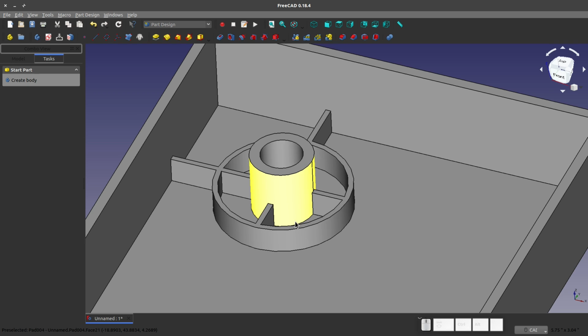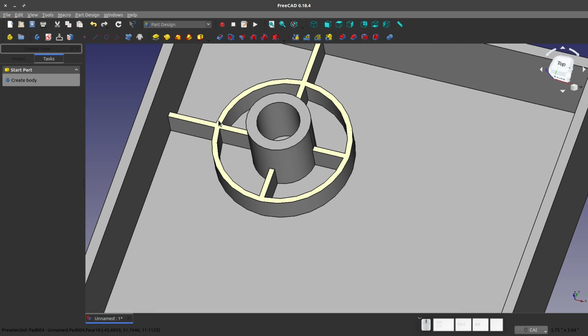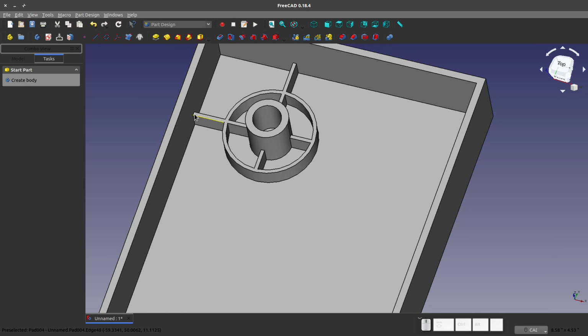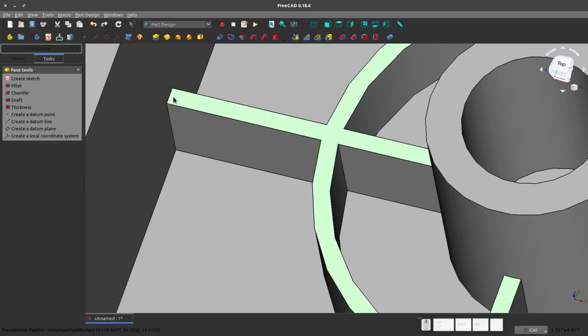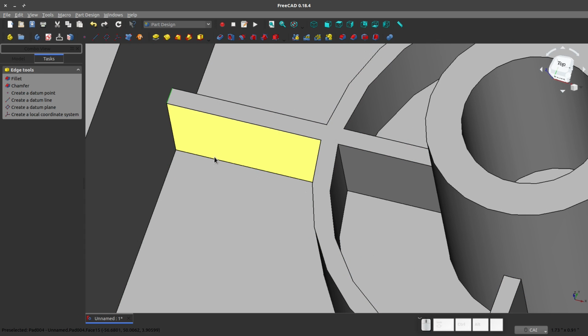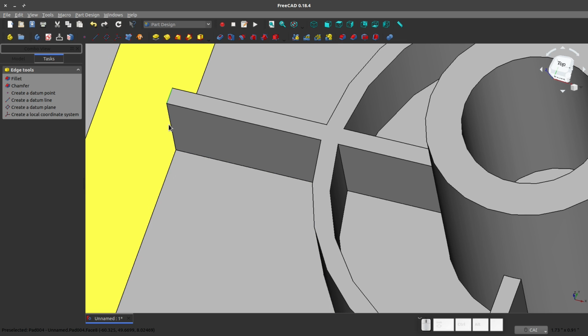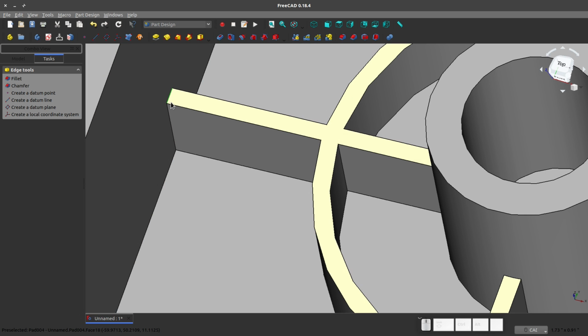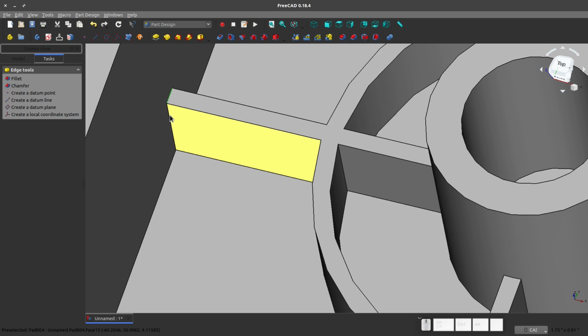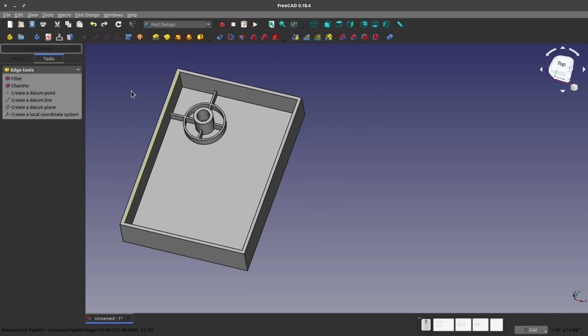4-way intersections between ribs. So here I've got a 4-way intersection. This increases the risk of sink, so that's something that you need to know going in. And I notice I have my ribs connected to my sidewall. That's a double-edged sword. I can stop my rib short of my sidewall and not connect it, and the advantages of that are I get less sinks and void risk and less risk of weld lines. But the pros of connecting the rib into the sidewall is I get better venting, better rigidity in the part, and it can even eject a little bit better. So keep that in mind.